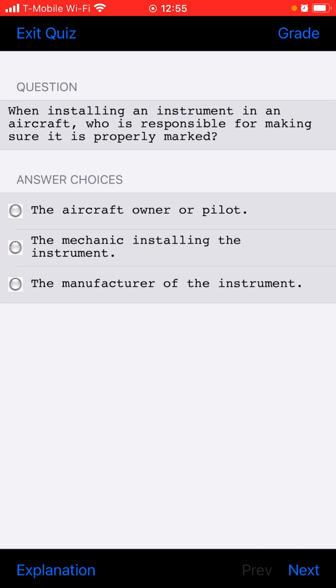What safety precaution must be taken when removing a wheel from an axle or when disassembling a wheel? Verify that the tire is completely deflated before removing the wheel from the axle or before wheel disassembly.